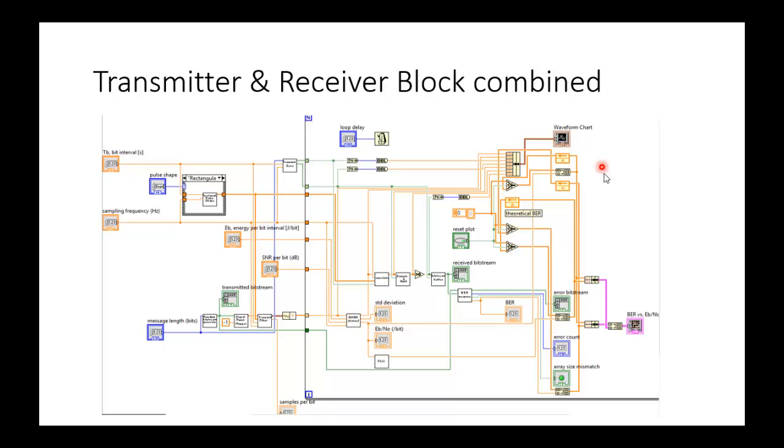So all this part consists of the receiver. First of all, it passes through the correlator. Here at the correlator, the signal is first multiplied by the same pulse shape that was used by the transmitter. The product is then integrated over a 1-bit interval. The correlation function is controlled by the sync bits so that the correlation occurs at the right time.